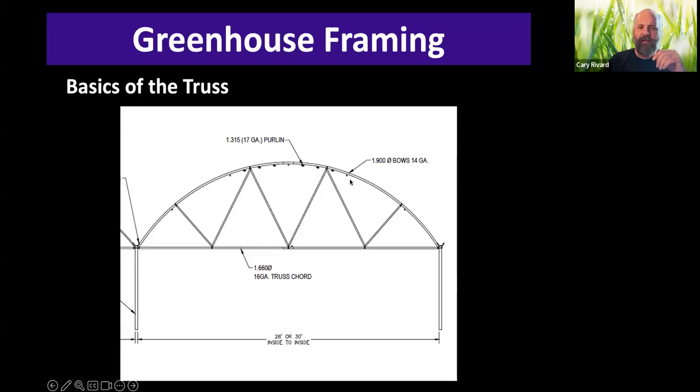And keep in mind that on this side, it's attached. And so as this pushes down, this side is actually going to pull up against it, right? And so they balance each other out and help keep it rigid. And no matter if you're talking about a Gothic style truss or a Quonset style truss, that W webbing that exists between the trusses is actually incredibly important.